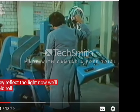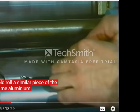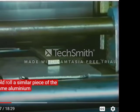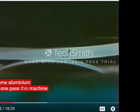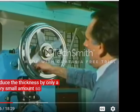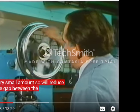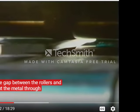Now we'll cold roll a similar piece of the same aluminium. In one pass, this machine will reduce the thickness by only a very small amount. So we'll reduce the gap between the rollers and put the metal through again.